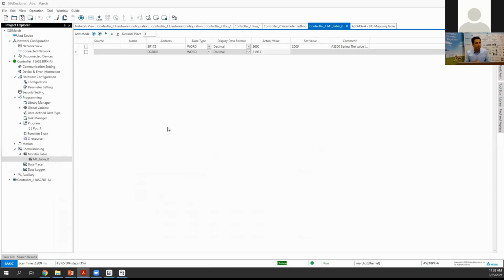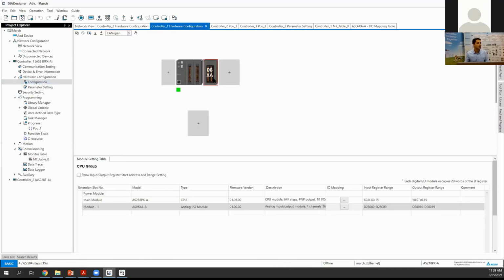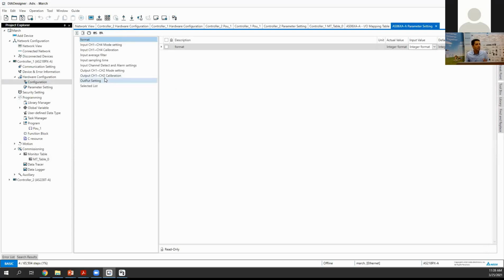So they are on different scales. Same value, both of them 10 volt, but different scale. Sometimes we want to work in the same range. I want to see exactly the same: if it is 10 volt, it will be 10 volt, if it is 5.0, and so on. For that, I will go offline and go to configuration again. We have two ways to do it.